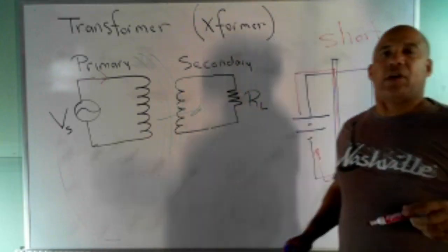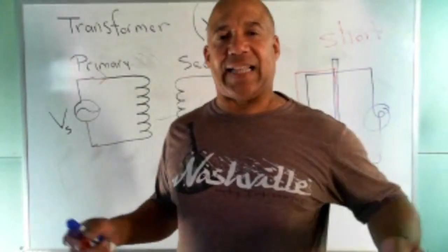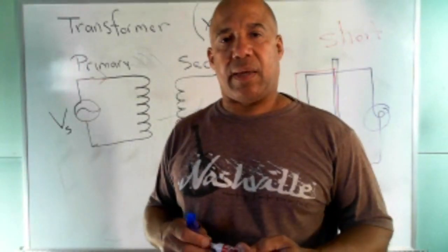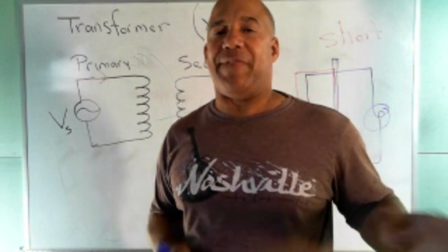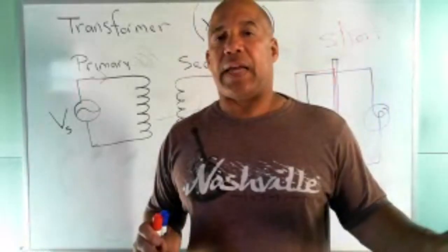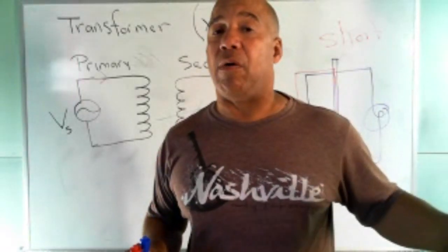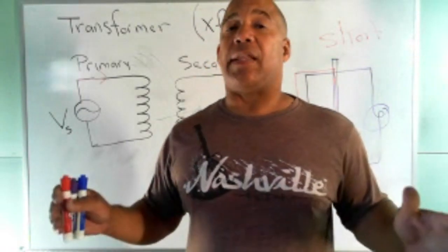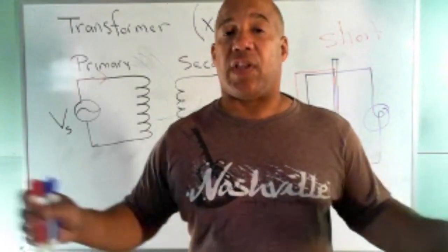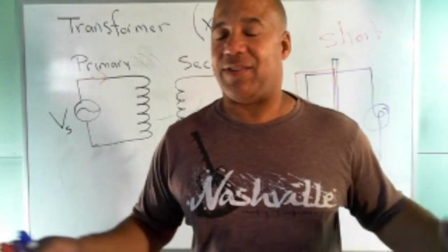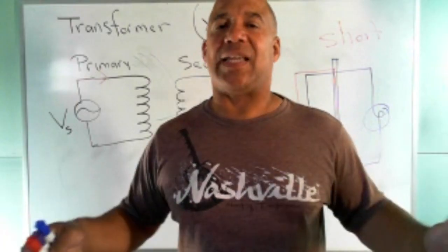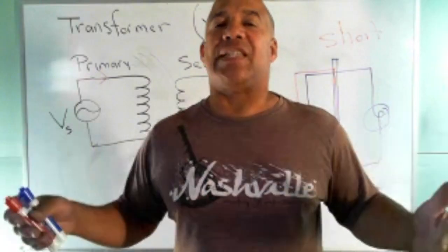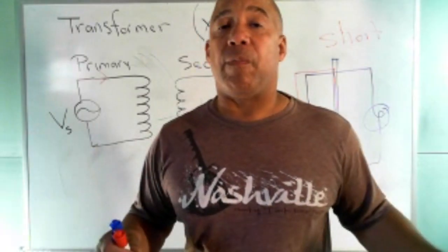It turns out that magnetic flux does exactly the same thing. Now get this, when they talk about current flowing, they call the opposition to current flow resistance. They call the opposition to flux flow reluctance. The R thing kind of gets me. But resistance and reluctance. Resistance is opposition to current flow.